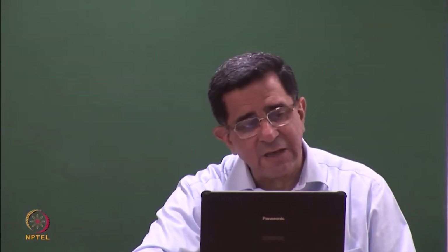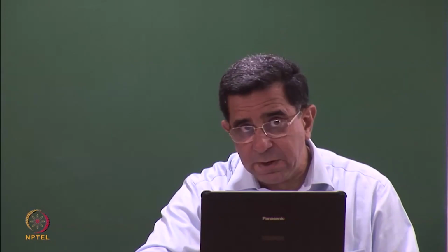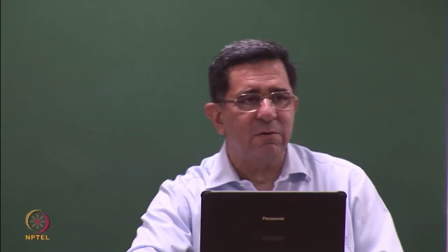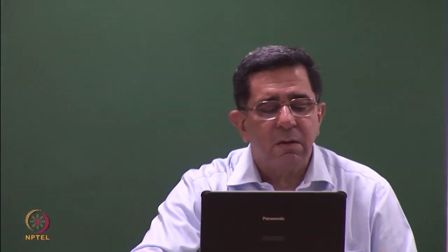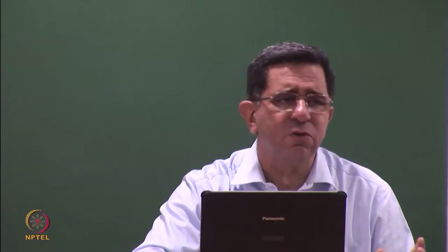So they came to us, there was an ash pond nearby, and we did extensive testing before we allowed this to be adopted, and we looked at heavy metals, we looked at every possible contaminant which would come, and we've used ash for raising low-lying areas. There are no issues of settlement, the engineering behavior is fine, permeabilities are fine. The only issue is erodibility.